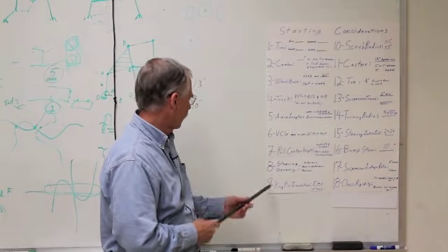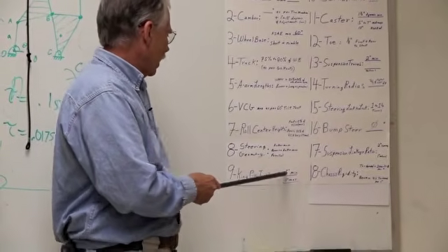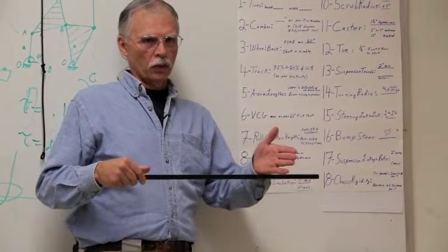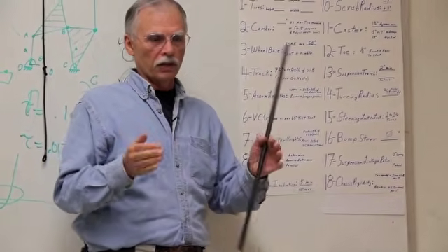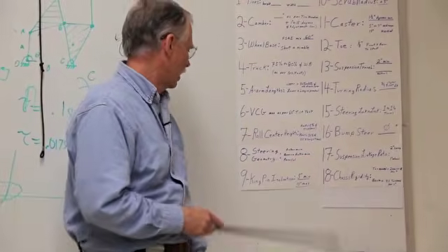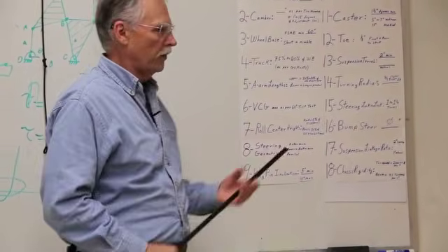All right. Number 9, kingpin inclination. Kingpin inclination returns the wheels to straight ahead when you let go of the steering wheel. It's for straight line stability. You have to have some. I would say a minimum of 5 degrees to a maximum of 15 degrees.